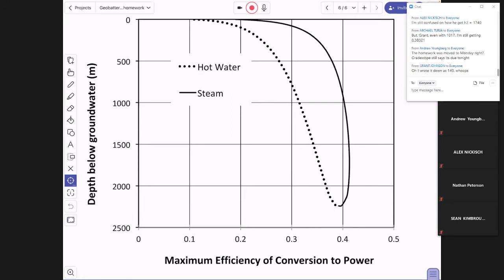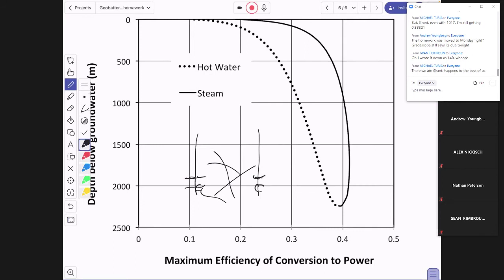And so they have these two wells that are put in, a well here and a well here, and they're injecting cold water here, and getting hot water coming in here. And there are these fractures all over the place. Are they going to intersect? Is all this water going to go up here and down here and miss all of that rock? So what they do is they hydraulically fracture it, and they bring the pressure in this injection well way high and just create these fractures to go like that.